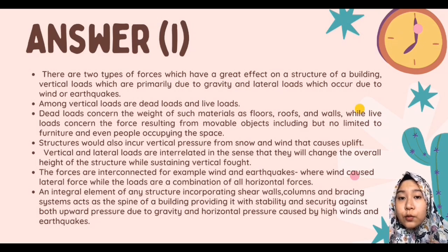Dead load concern the weight of such material as floor, roof and wall, while live load concern the force resulting from movable objects, including but not limited to furniture and even people occupying the space. Structure will also incur vertical pressure from snow and wind that causes uplift. Vertical and lateral load are interrelated in the sense that they will change the overall height of the structure while sustaining vertical load. The forces are interconnected.